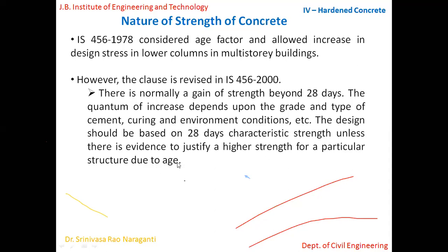That means if you are using different materials, as a concrete specialist, if you know that, okay, concrete is going to gain strength substantially even after 28 days, then you take that strength, provided you are able to justify it. We'll be able to justify if you use different materials. I think you studied, right? If you use silica fume, or especially fly ash, those materials along with the cement, fly ash has a property to gain strength in the long term. Maybe after 60 days, after 90 days, you see more strength if you use fly ash.